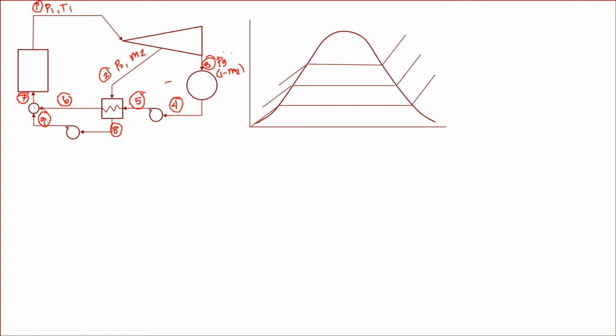So how do we do the analysis of that? This one is your 0.1. This is your pressure 1, pressure 2, pressure 3. Also, it expands, okay, producing work. Turbine 1, 2 to the point 2, where a mass M2 has been extracted. Okay, and further producing work to the point 3, where work turbine 2, 3 is produced, but the mass is now 1 minus M2.